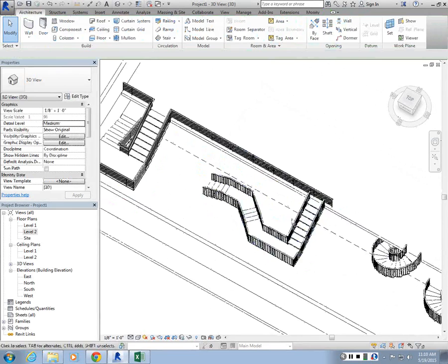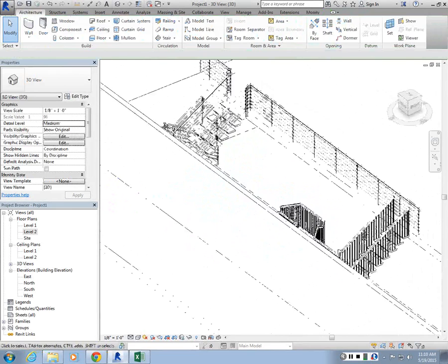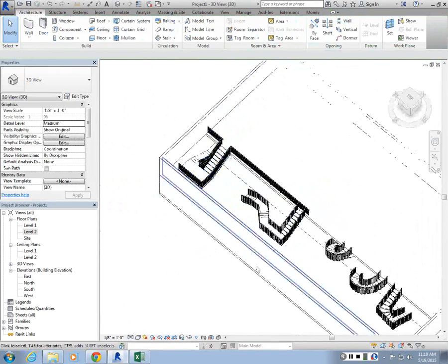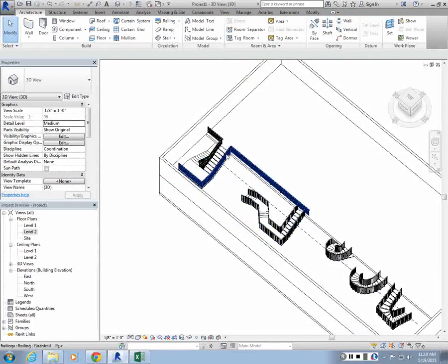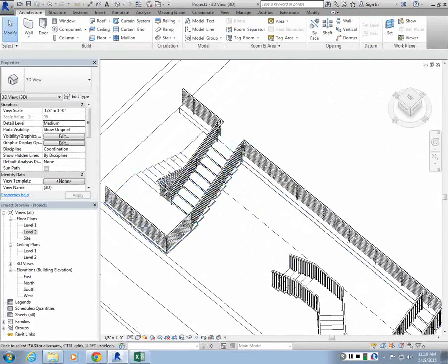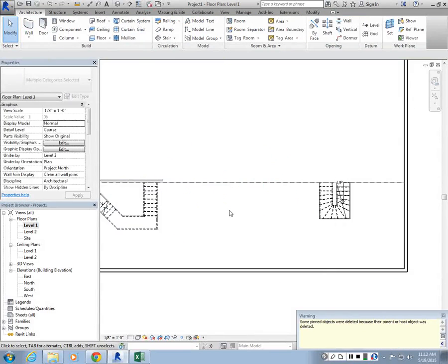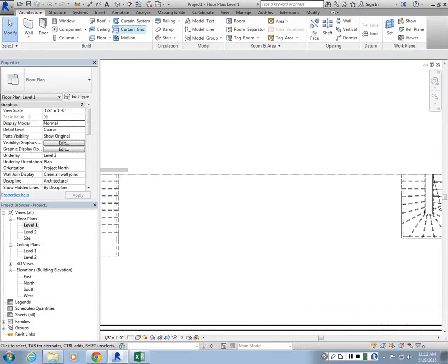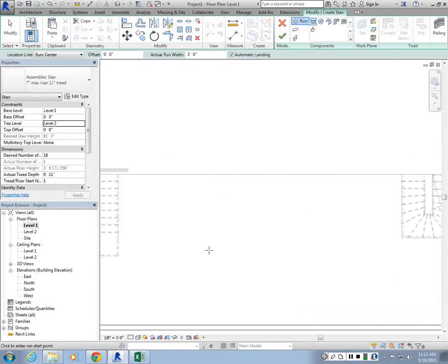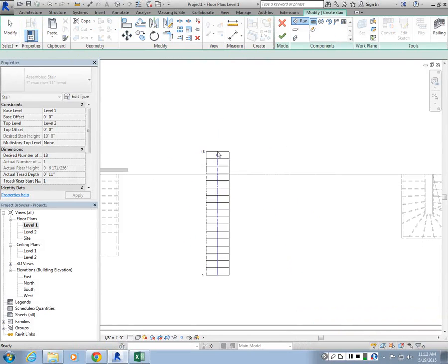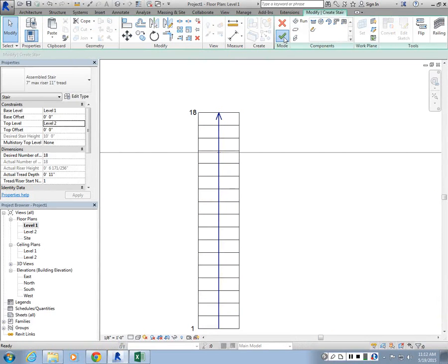Alright? So create some stairs, mess around with these customization tools, play with the railings, so extend them to the floor slab, make them continuous. Just going to delete these for now. Go to stair, run, and let's say this is a linear element, hit check.